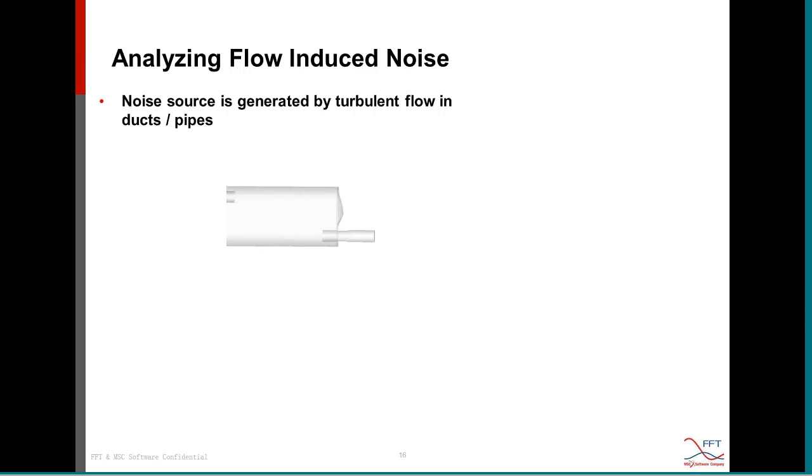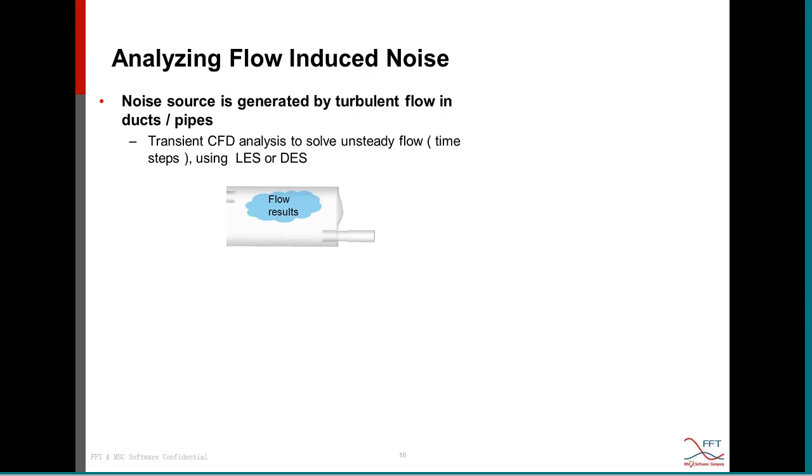Okay, so we have been talking about sound propagation in the duct, and the source is often from engine pulse, for example. Now, in this slide, we are looking at another type of source, which is flow-induced noise inside the volume. So apart from the source from the upstream engine, we can also have this flow-induced noise that is generated by turbulent flow inside any volume or duct system.